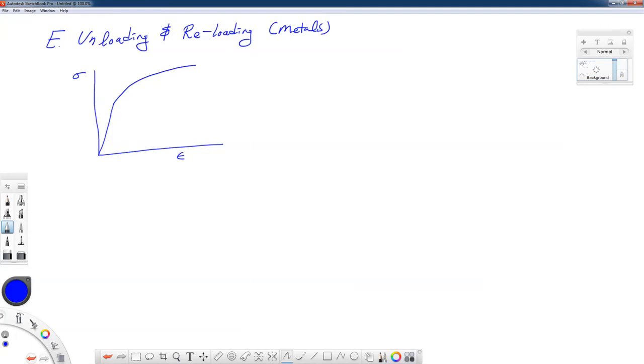So we've previously talked about plasticity, the stress-strain curve, the Ramberg-Osgood equation, and Newton-Raphson iteration to determine stress given a certain value of strain. We're going to continue on talking about uniaxial plasticity with uniaxial cyclic loading of metals. Let's first talk about the basic unloading and reloading behavior of metals, where we don't yield them in compression, but then we will get into a little bit more detail about cyclic loading, the cyclic stress-strain curve, and the Masing